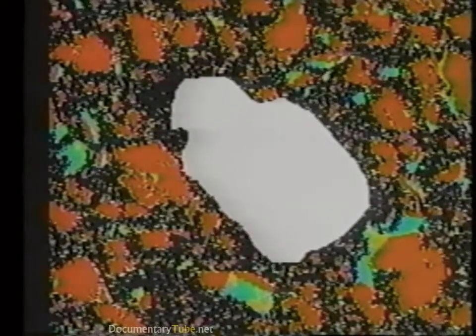After a cycle of dissolution, diffusion, and precipitation is complete, the computer proceeds with another cycle. As this process repeats again and again, the microstructure develops, building bridges between particles that provide strength to the material.